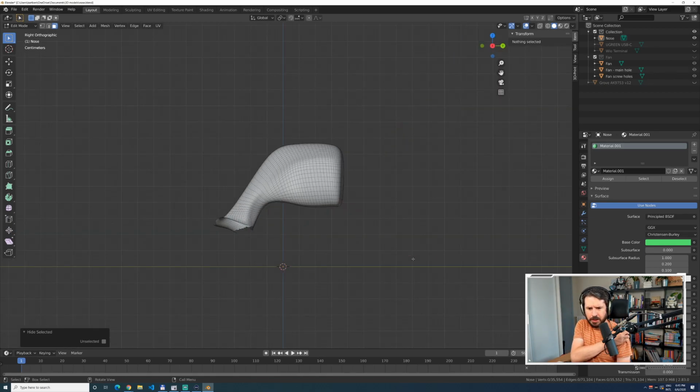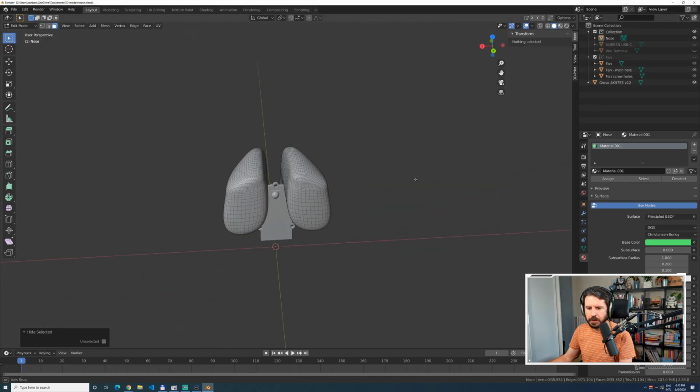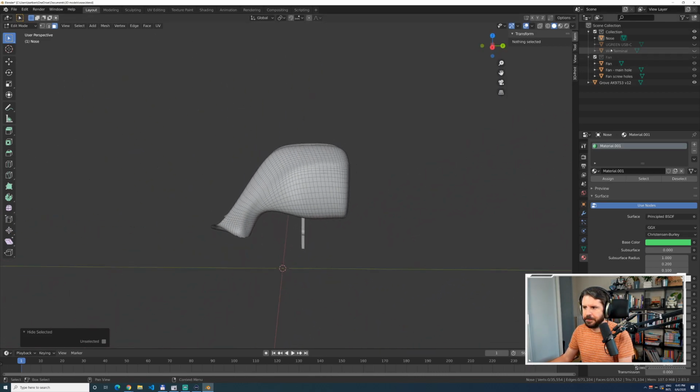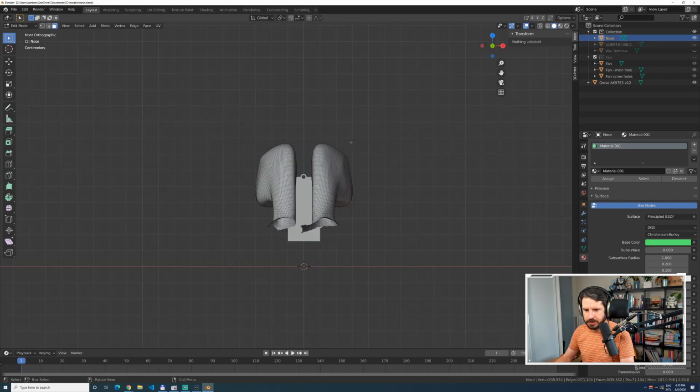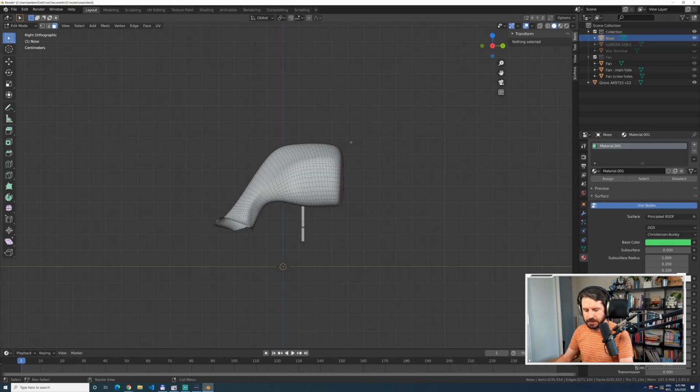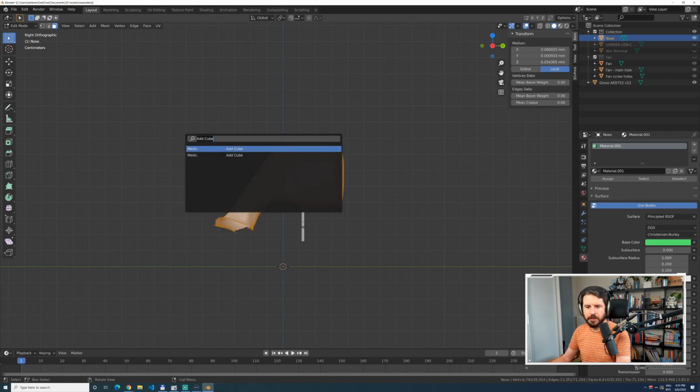Like I was saying, there's too much. I'm going to have my sensor somewhere right in the middle of the nose, so I need to make some space for it. What I'm going to do is select everything and press F3. That's a shortcut I mentioned before, giving you access to all the tools available in Blender. That's actually a good way to learn. You can just make a guess: is it possible to cut the thing in half? Well, maybe I cheated because I knew that it was called bisect.